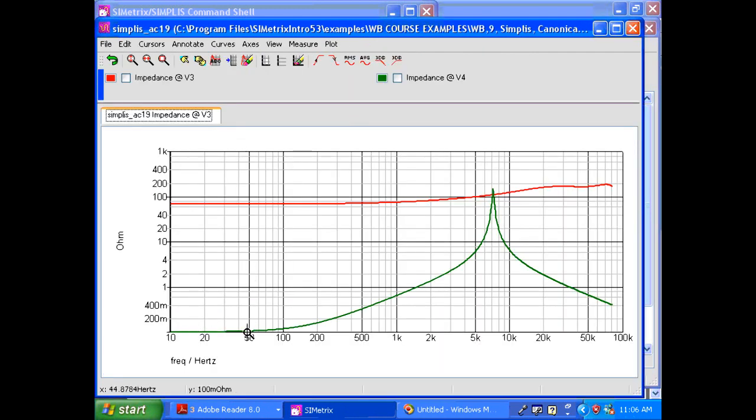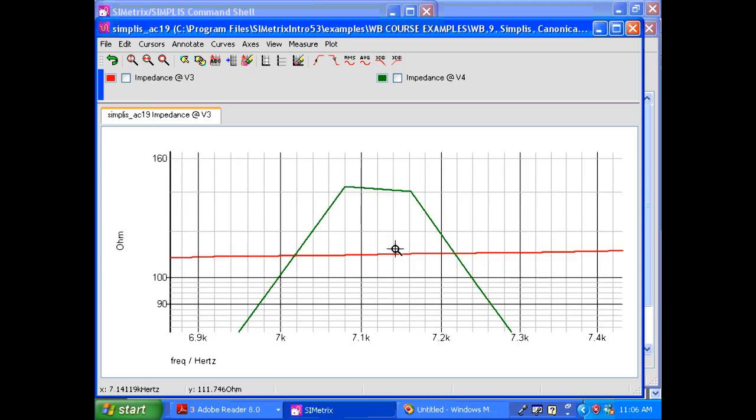And we're looking at the magnitude of the filter impedance, looking into the filter from the power supply side. Now the rule is this curve should never exceed this curve. That's the rule. If it's down below, even down here, we can see some effect from it. We're going to show you that in just a moment. So let's save this. This is when we had a problem. In fact, we'll expand that just to show you.